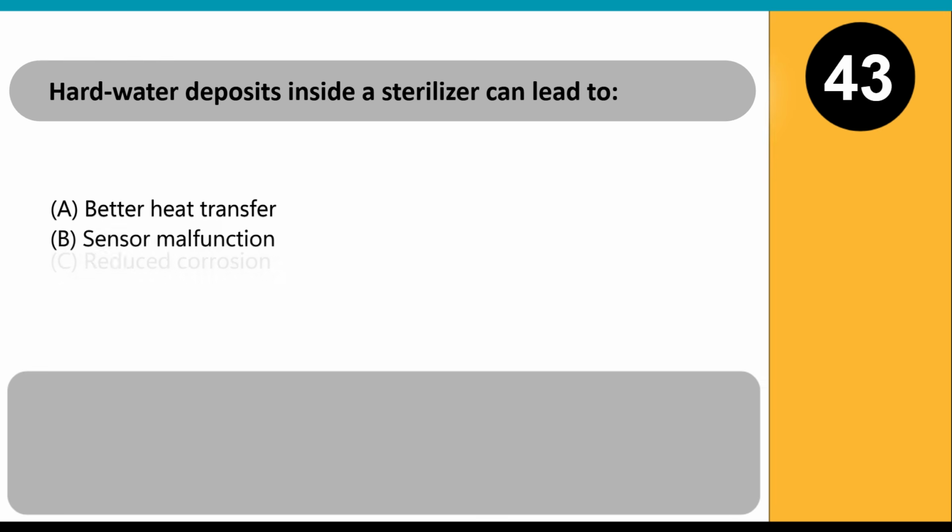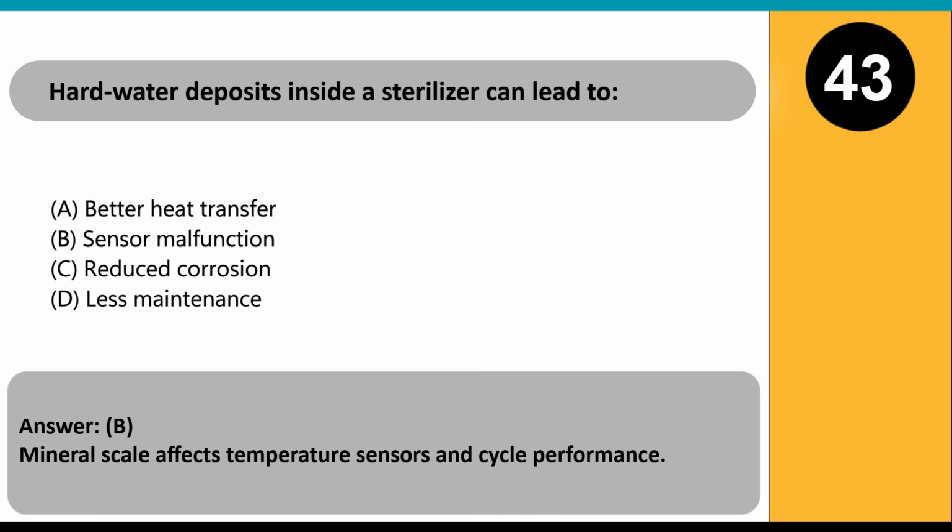Hard water deposits inside a sterilizer can lead to A. Better heat transfer. B. Sensor malfunction. C. Reduced corrosion. D. Less maintenance. Answer: B. Mineral scale affects temperature sensors and cycle performance.